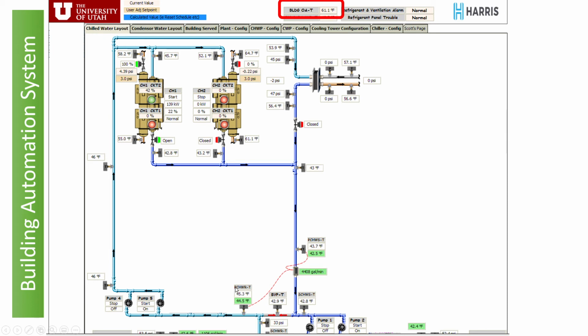The other thing I can show you here is the heat exchanger. So if we skip the chiller, the water goes through the heat exchanger, gets cooled from cooling tower water. And then these are the pumps. These are the pumps that are downstairs, circulating water through the chiller. These are the pumps that are upstairs, sending it out to the building.